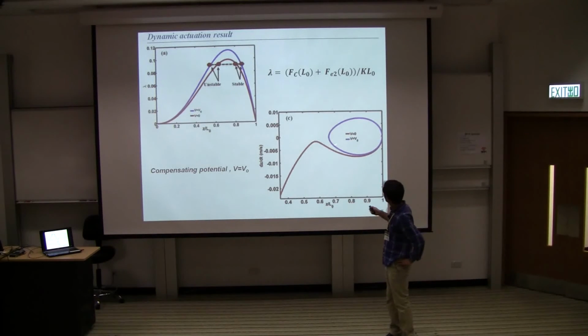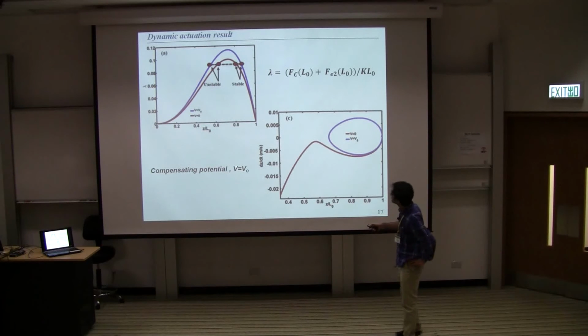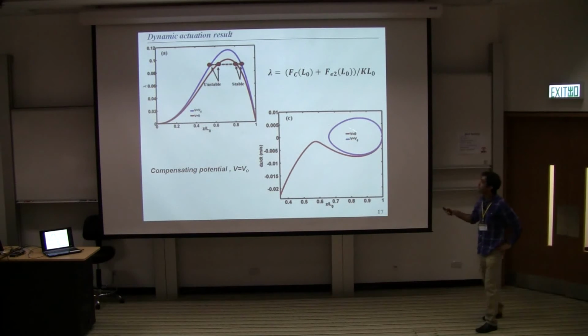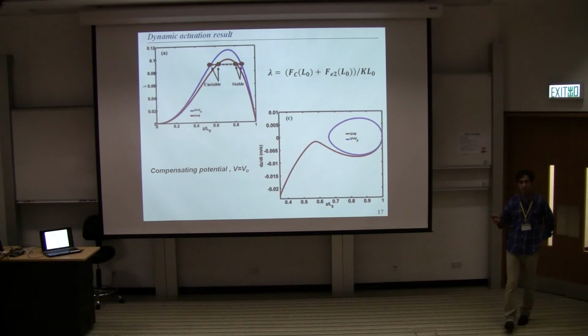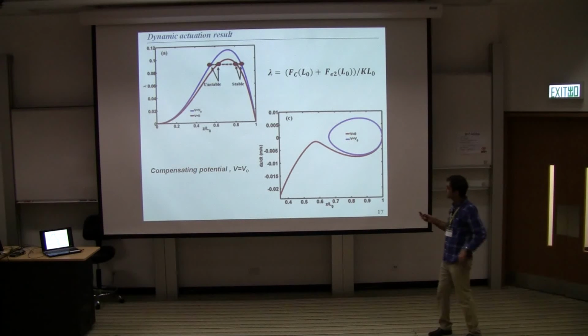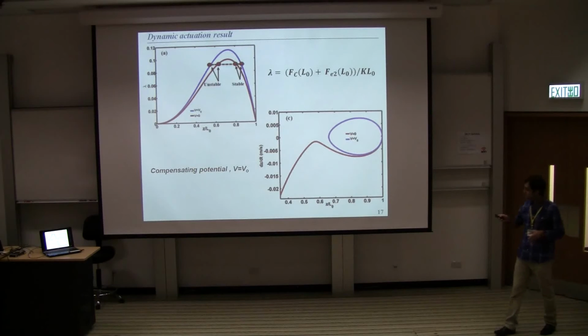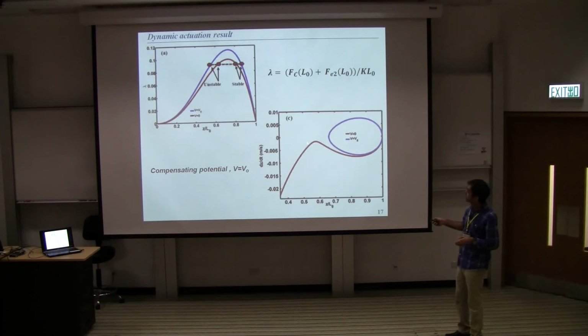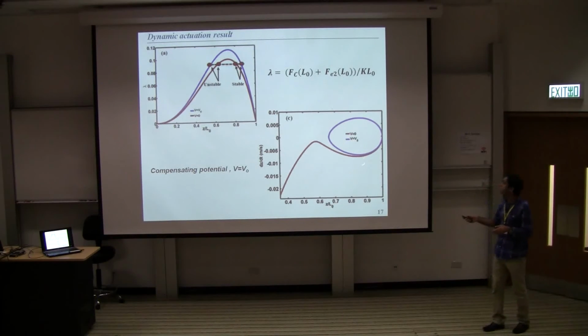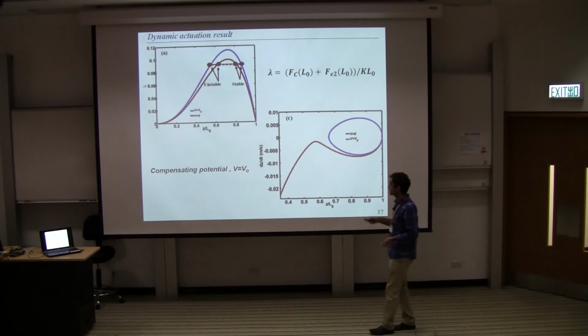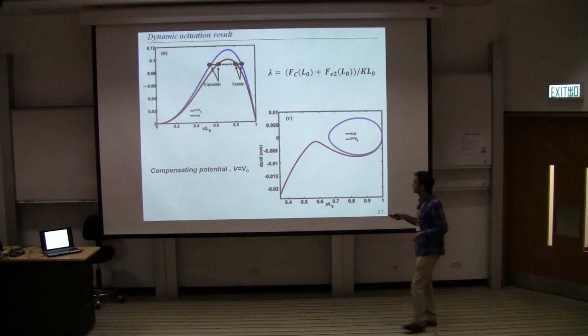When we compensate the contact potential, we have a closed orbit, which shows that the spring constant is strong enough to counterbalance the other forces. But if we don't compensate, it's the red one, which shows that the sphere went to stiction, so the system is unstable.